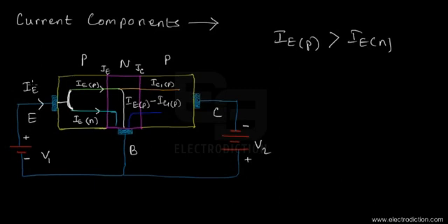And on the other hand, another current component due to the minority carriers, that's the holes present in the base, would flow into the collector terminal from the base terminal due to the applied reverse bias. Okay, and now together they'll constitute the reverse saturation current flowing in the collector section, denoted with the symbol ICO.